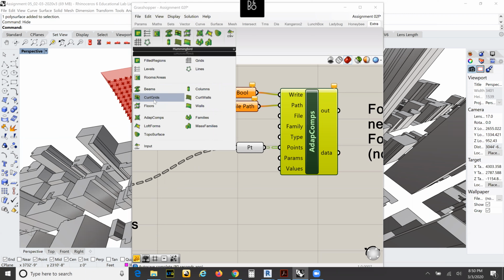Also, if you have a longer face than the other, sometimes Revit will justify the curtain wall to a specific edge, and now instead of going true perpendicular, like up and down, it becomes perpendicular to that edge, so everything becomes slightly slanted.